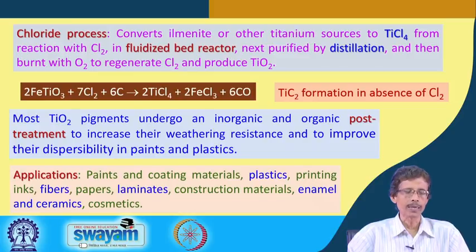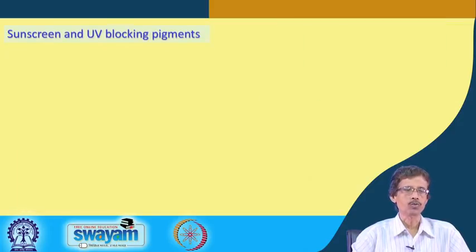Where we want some glossy type of surface, we add some titanium dioxide based inorganic white pigment. Then the formation of the enamel surface and the ceramic surface: we all know that the white ceramic and enamel based cookwares we use in the kitchen are all white. So, titanium dioxide is the most favored inorganic pigment for making those enamels or ceramic materials, and sometimes like your toothpaste, we can also add it to different white creams and pastes for the cosmetic industry also.